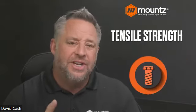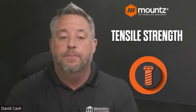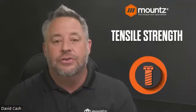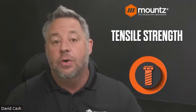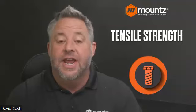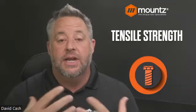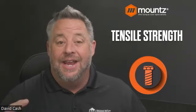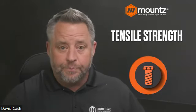Now, when we talk about the fastener being able to stretch, that stretch relates to the tensile strength of a particular fastener. Each one has its own unique properties on how much it can stretch before it reaches the yield point or actually breaks. This is another thing that we need to consider when we are using torque.